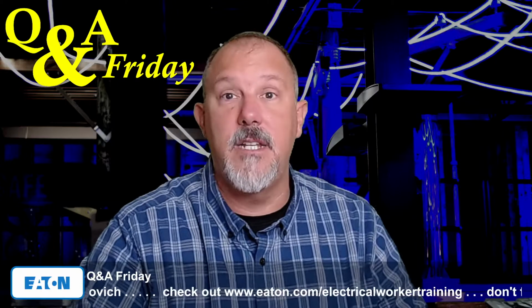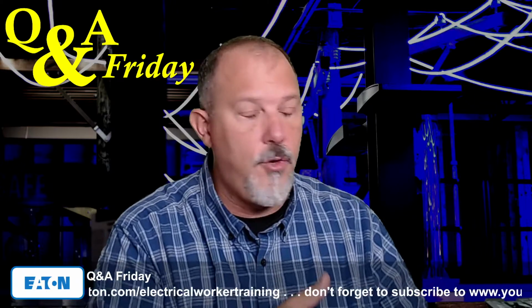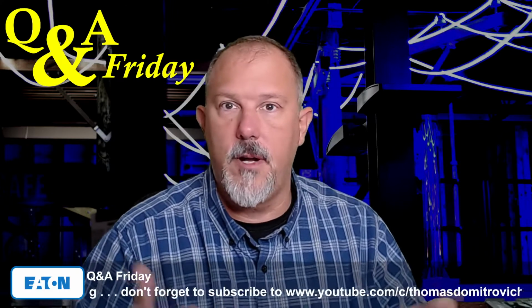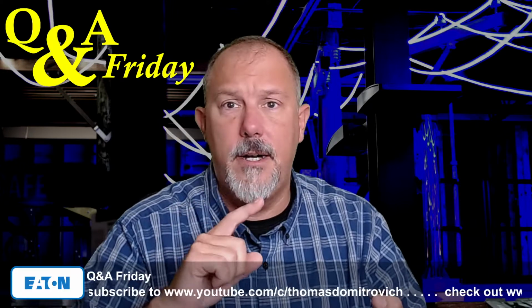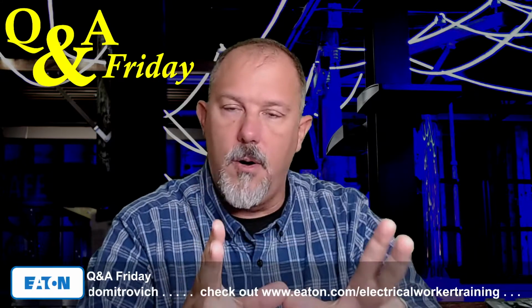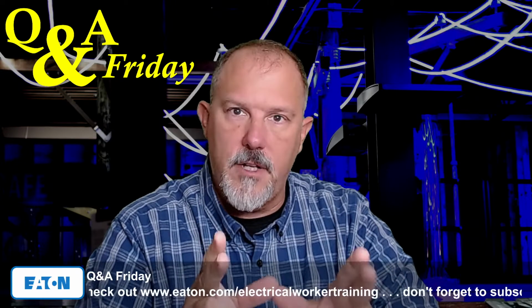What's it listed as? And if it's not listed, then I would say you might have other issues, because the AHJ is going to tell you you made a homemade enclosure. How are you going to show that it meets the requirements of your SCCR ratings, your clearances, all that good stuff? So I wouldn't go there, JW. I would go back to just a blank box in the wall and look at all of the different areas of requirements.